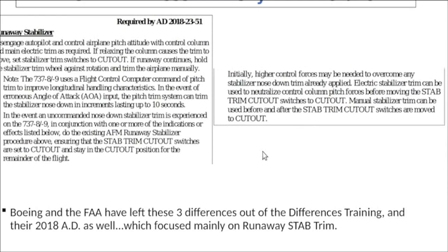Having the speed trim system not shut off would really be a strange thing if you had your 15,000 hours of having it different. Also, this control column cutout: if you pulled back hard enough, it would stop the speed trim too. In this case, the speed trim kept right on going because they needed MCAS to keep active too.